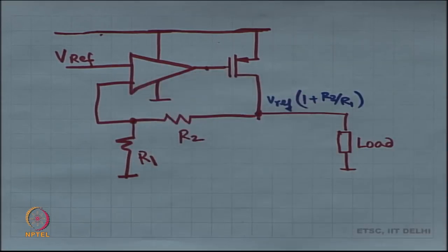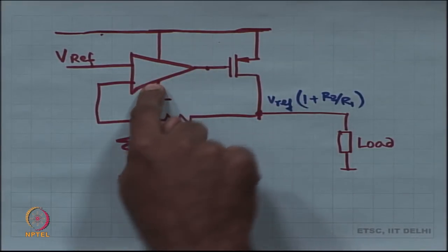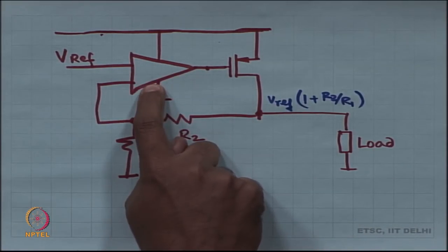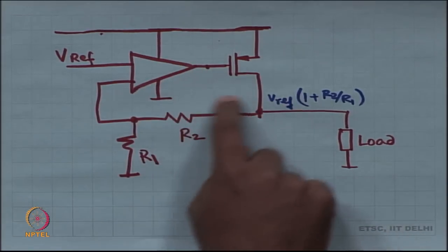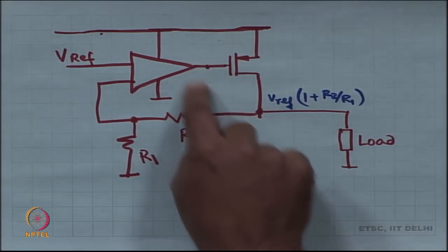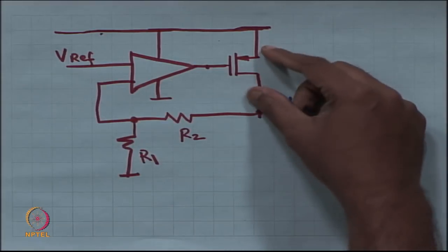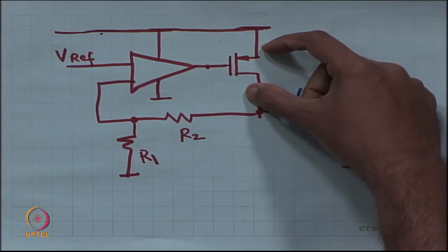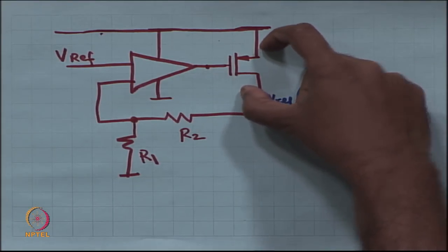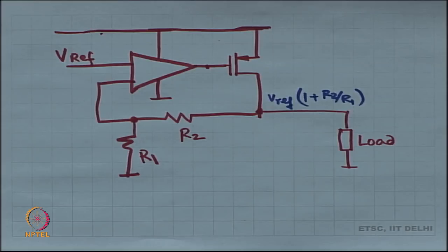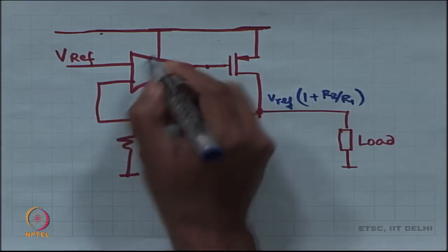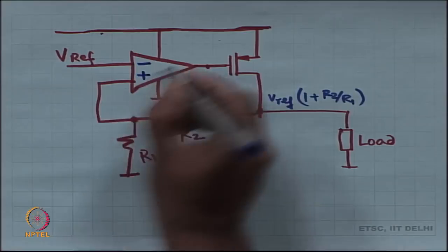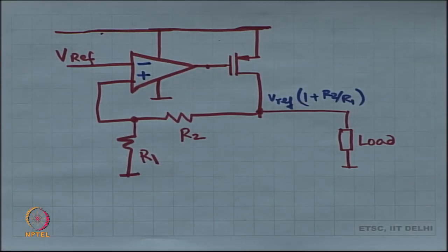If I do the same signs as before, that is plus on top, minus on the bottom, then unfortunately, this is an extra inverting amplifier, a common source amplifier. This is going to invert once again, you are going to end up with positive feedback. So, instead what we are going to do is place minus over here and plus over here. So, you flip the signs and that should be enough.